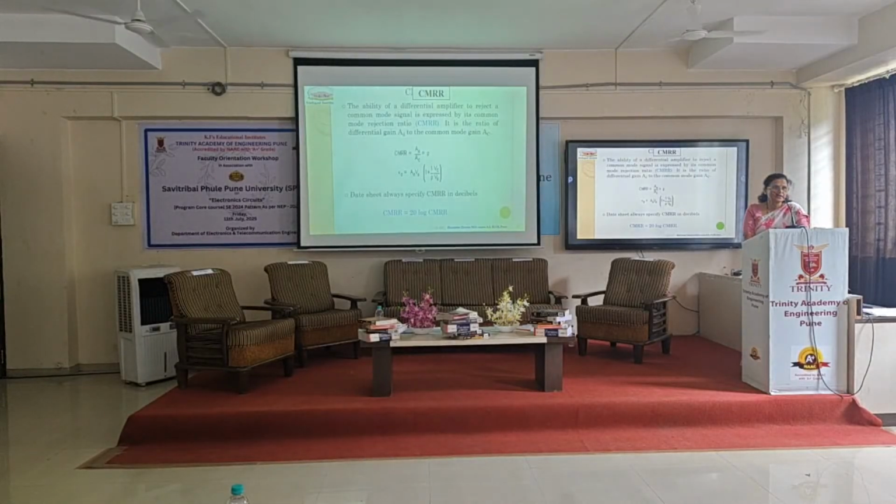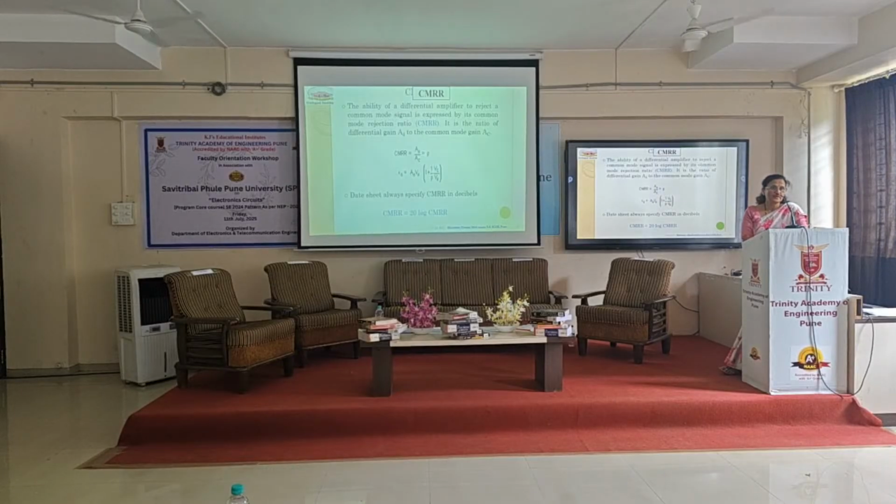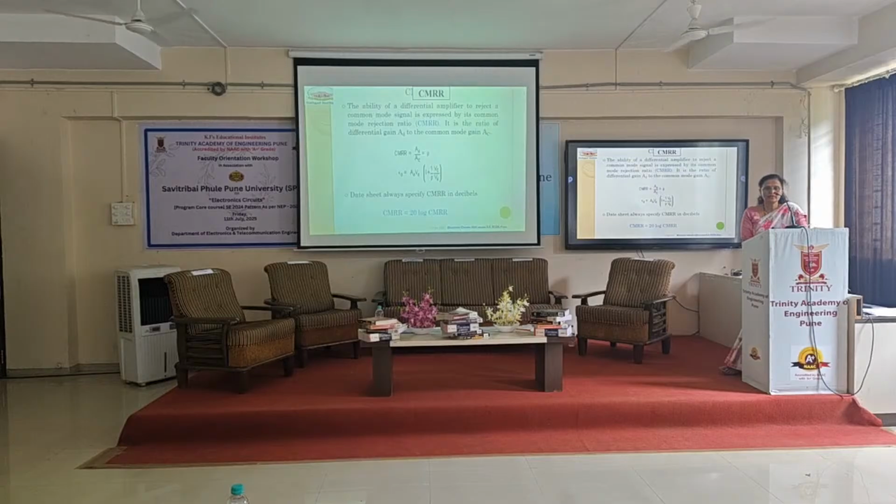And in this, there is need to explain a few more traits on CMRR because it indicates the noise rejection capability of the operational amplifier. It depends upon the differential gain and common mode gain. Whatever points we have discussed up till now, we are saying the operational amplifier amplifies the difference between two signals. But at the same time, we also consider the average value of gain. Whatever the common signal, that also gets amplified and that gain is denoted by AC.